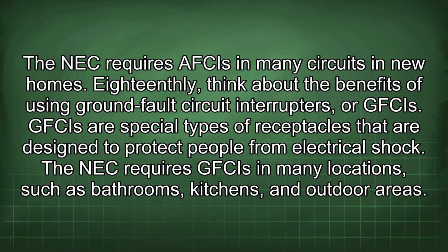18thly, think about the benefits of using ground fault circuit interrupters, or GFCIs. GFCIs are special types of receptacles that are designed to protect people from electrical shock. The NEC requires GFCIs in many locations, such as bathrooms, kitchens, and outdoor areas.